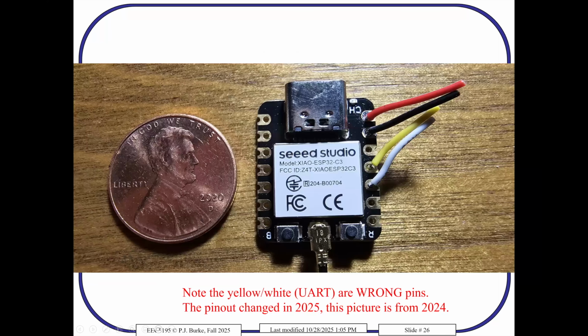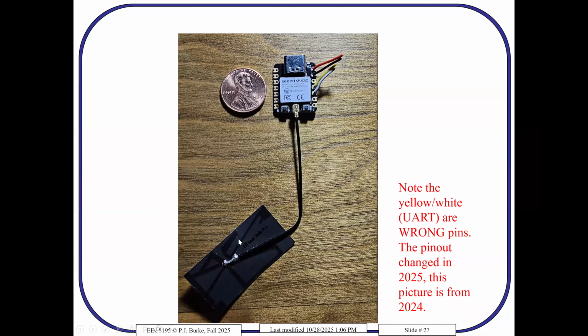There's a picture. This is the antenna. Never power up a radio without the antenna connected. You might fry the radio. This is a very fragile connector. You have to put it straight on and pull it straight off. If you come in at an angle, you'll bend the pins and then you've bricked it. Don't ask me to fix that. I think I would just throw it away and give you a new ESP32. So there's an external antenna. The radiation pattern is in the direction of the wire that's on top.